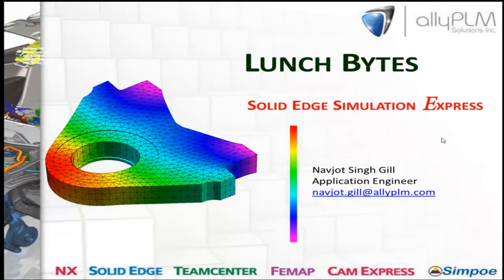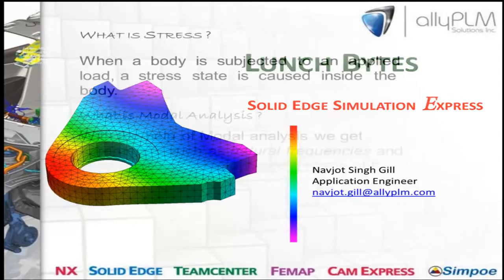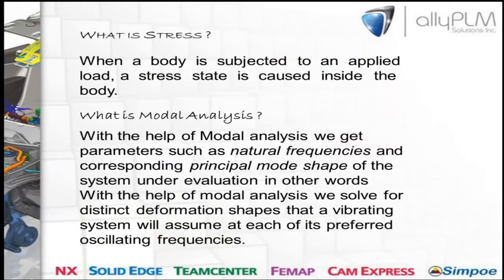Once again, today's topic is simulation. Before we get into more details about the workflow inside Simulation Express, some of the terms which I'll be using today will be stress and modal analysis. So what is stress? When a body is subjected to an applied load, a stress state is caused inside the body. The load could be a force, a pressure, temperature, etc.